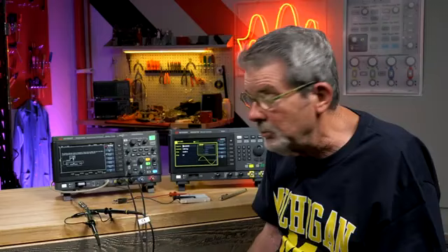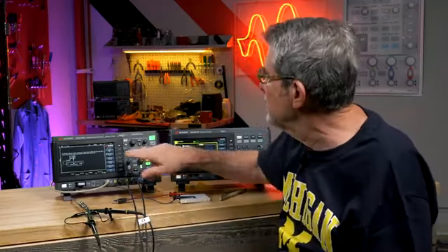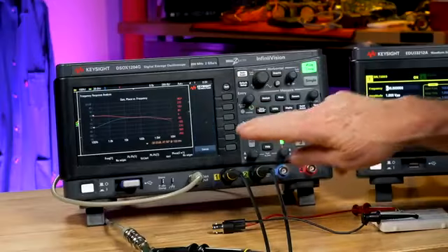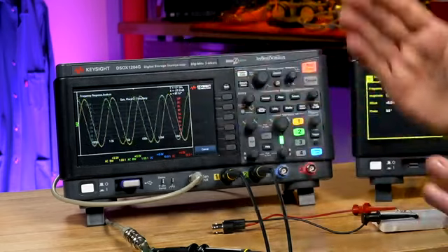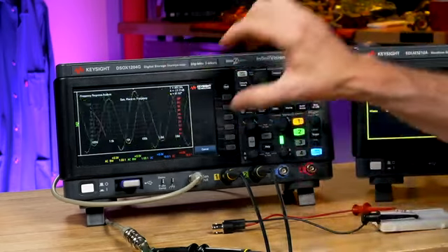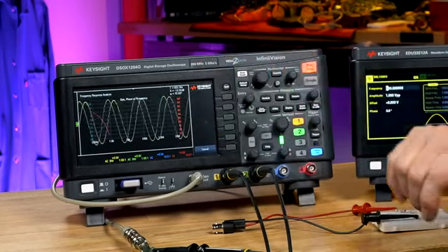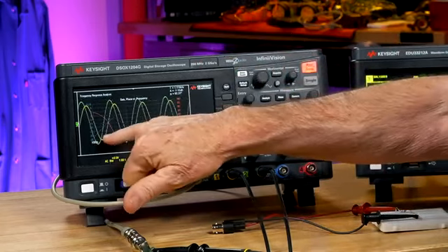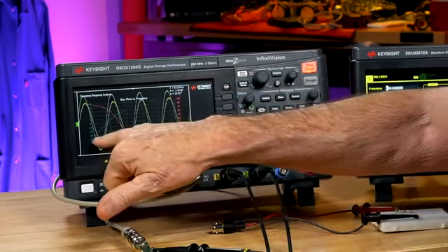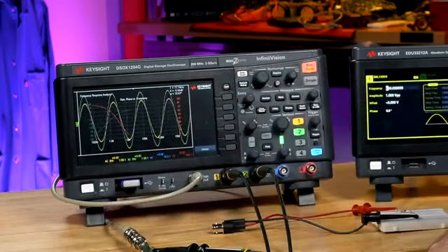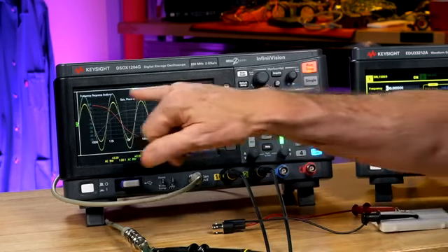When I did it manually, I think I did 16, and when I did it last night, it took me a good 15-20 minutes. This will do it much quicker. Then we just press Run Analysis. It automatically scales at each test point, both the vertical and horizontal, and it begins plotting. The blue trace here is the gain trace. It started right around minus 30 dB, which is what we expected.